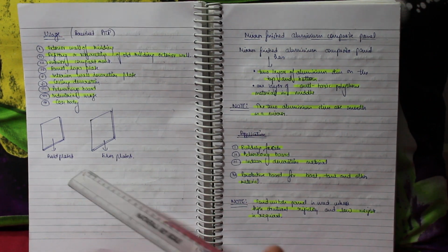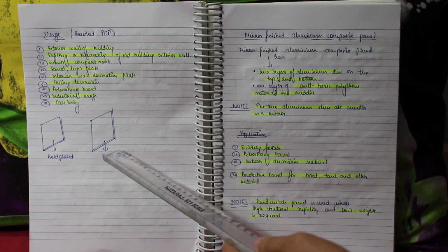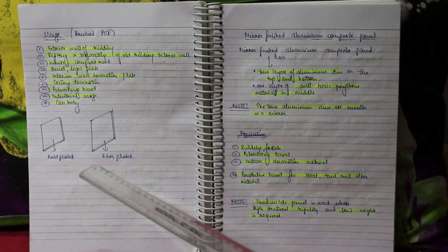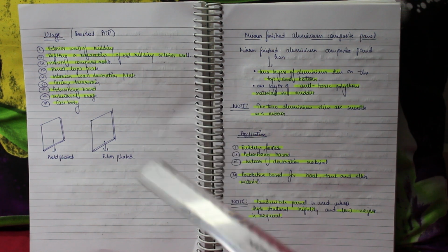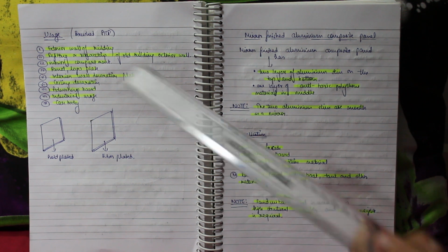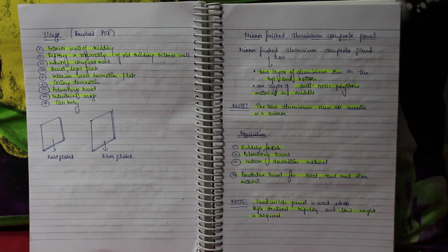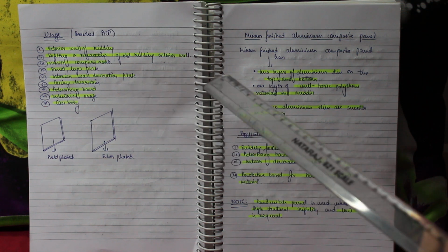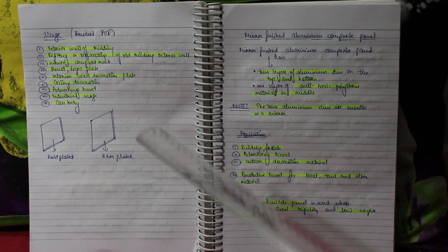I cannot really paint, that's the reason I was not able to show you the color, but both will be of the same density, same thickness. As I said, ACP's thickness would range from 0.3 mm, 0.4 mm, 0.5 mm, and could go up to 1 centimeter or so, depending upon the usage. And what exactly is the usage of brushed ACP? First of all, it is used in exterior building walls. When I was talking about the facade, that's what we are talking about here, and it is used for refitting and renovating.